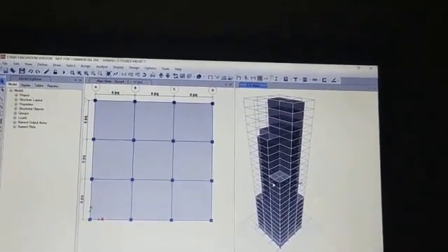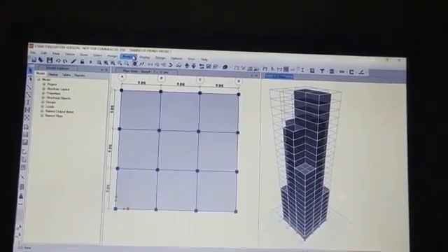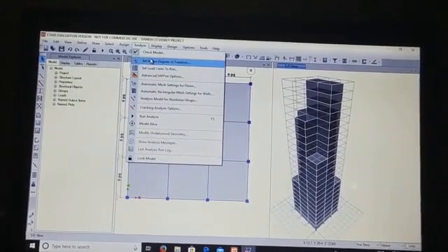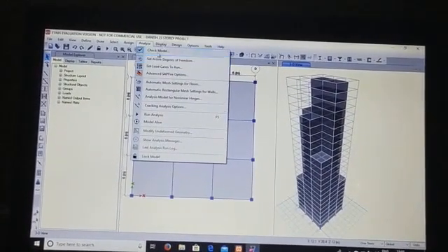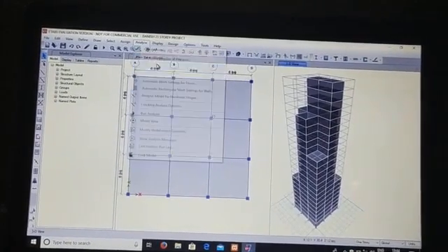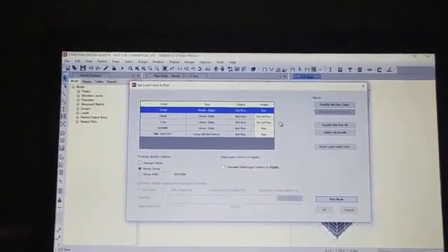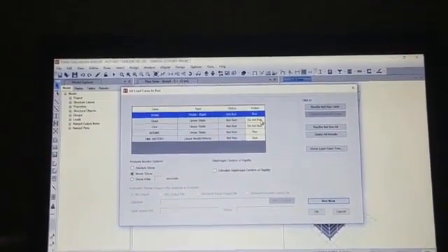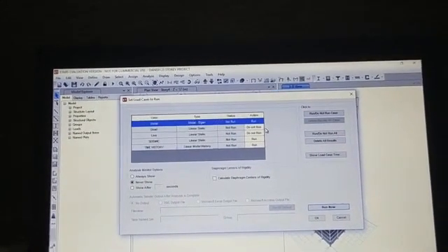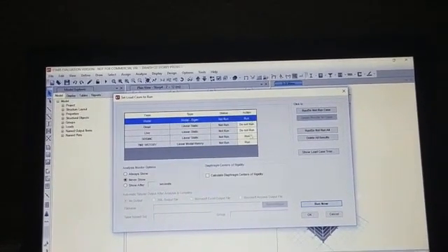Okay. Now after adding this, we will, as previously done, analyze the model. In that, first we have to set load cases to run. As we do not require dead and live action, we set them to not run as previously done, and the others we have to run.